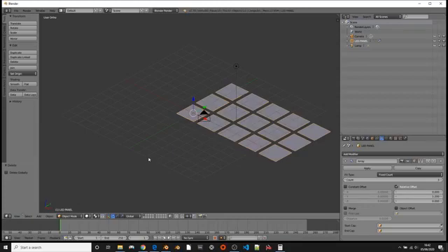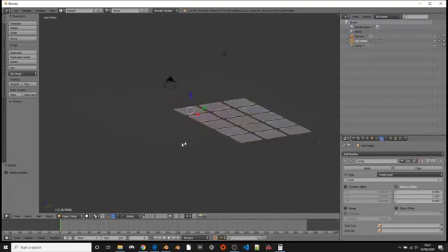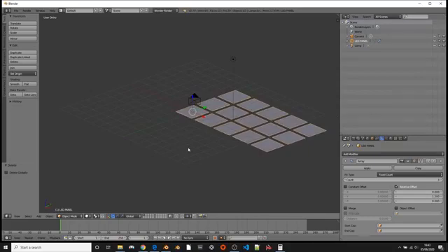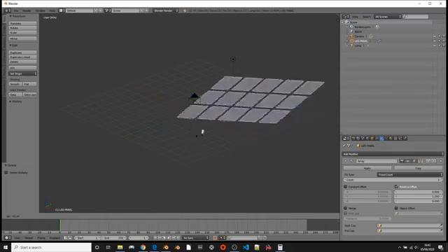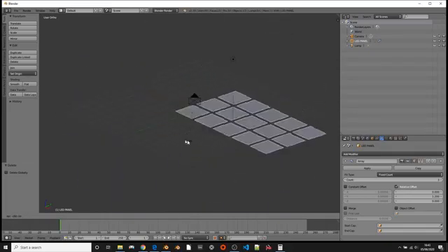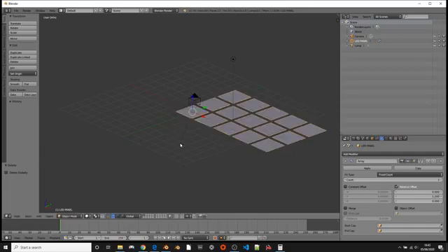So what I'm going to do, let's rotate it round. Now, with a lot of the tools in Blender, there are keyboard shortcuts that are quite easy. So I know that if I want to rotate, I can press the R button. Press that and it's going to rotate around the center. If I right click or press escape, I can get out without applying it.